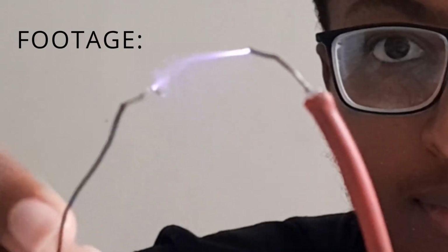For this purpose, I'm gonna use my ZVS driver. And I think the best way for us to alter its own frequency to make it audible is by connecting it with an amplifier. That's the best way we can do it. Because we cannot alter the frequency as we like, because we need a variable capacitor and a variable inductance to match the frequency that we want. Which means we have to change it, like so much work, and it's much more difficult.